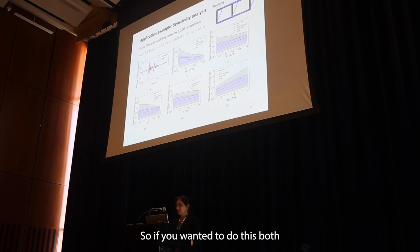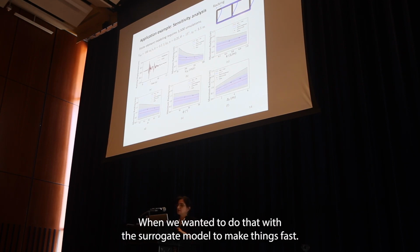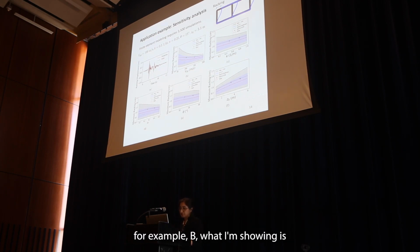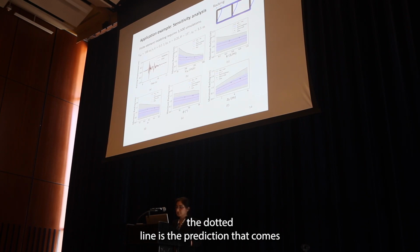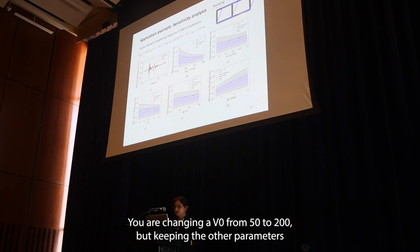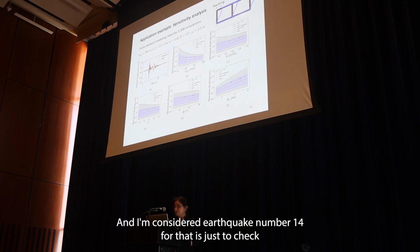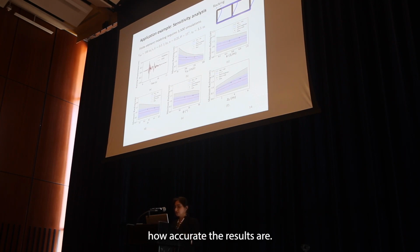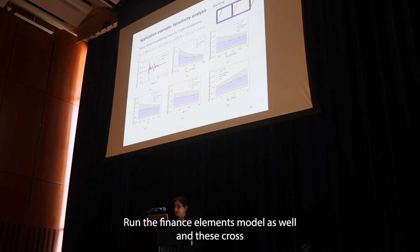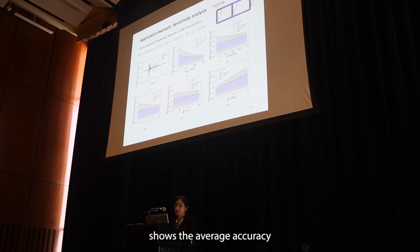If we wanted to do this by finite element analysis, we needed to run 3,500 cases, but we wanted to do that with the surrogate model to make things fast. So here, in figure B, for example, what I'm showing is the dotted line, the prediction that comes from the surrogate model for the case that we are changing VS0 from 50 to 200, but keeping the other parameters at their nominal values. And I'm considering earthquake number 14 for that case. To check how accurate the results are, we ran the finite element model as well, and these cross dots show the results that come from the finite element, which shows the accuracy of our model.